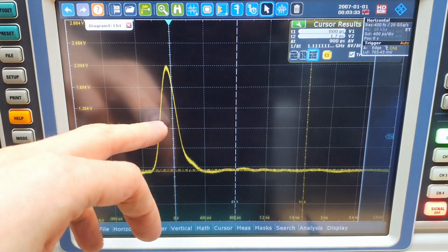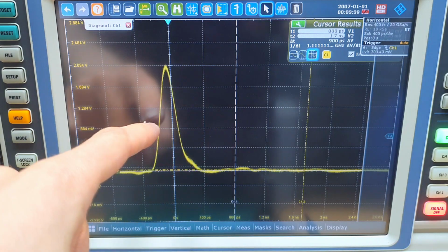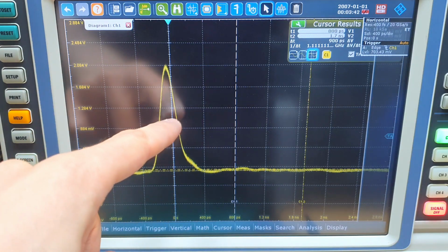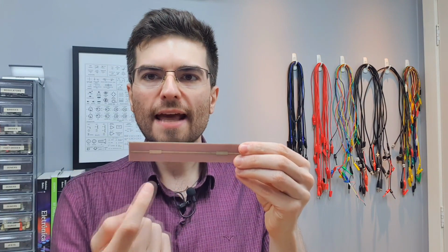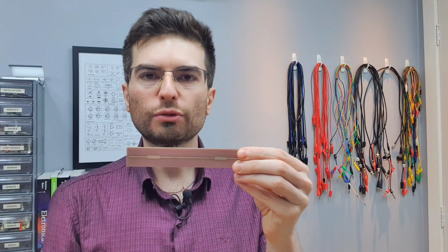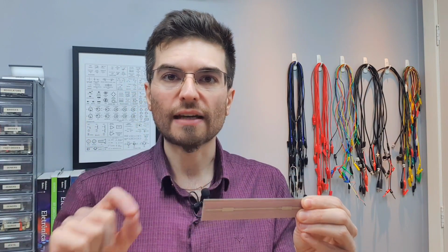We can see that the generated pulse is very clean, and it has approximately 200 picoseconds from the midpoint of the rise edge to the midpoint of the falling edge. And indeed, it needs to be very short because this defines the time resolution that we have to distinguish different features over the geometry. So imagine that if the pulse is larger than the time difference of the transitions, we would not be able to see the different features in the time trace. This is very similar to the resolution bandwidth when we are dealing with a frequency domain measurement.